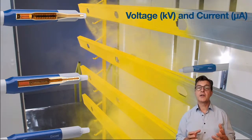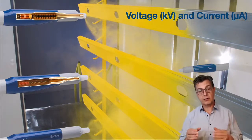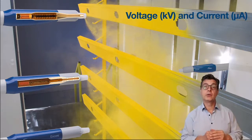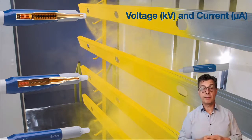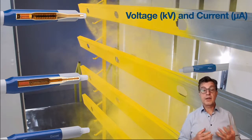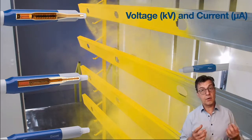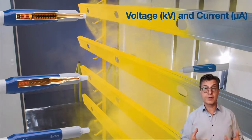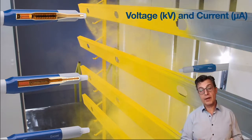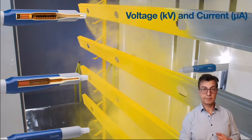Their design doesn't change much from one manufacturer to another. In fact, it's probably difficult to tell that the two multipliers shown in this picture are of two different makes. The high voltage multipliers of different suppliers can nevertheless differ in the quality of the components used and the quality of insulation and the potting, all of which affect their reliability and their cost.